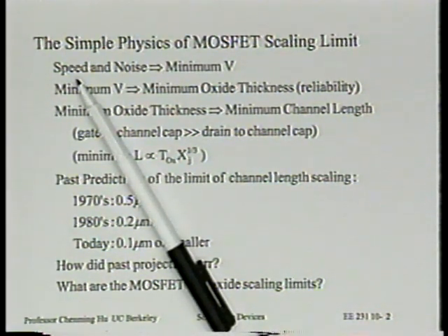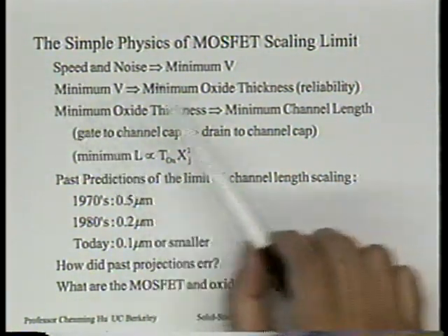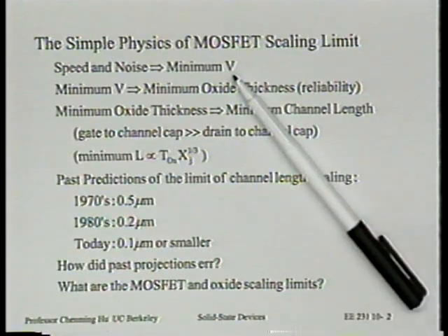The example he uses is perfect. Right now, no one sees how we can tolerate 0.1 volt VT. It just gives us too much leakage current. This is the point we've seen already, all right? Yeah. So put all this together, let's say 1 volt is a number. I'm just using it as an example. If you want to choose 0.8 volt, no problem. We can use that number also.